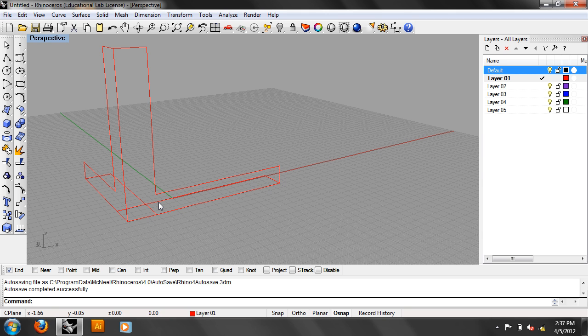If you want to try that with your drawings, what you could do is, for our house, let's say, you trace the edges of our facade, but instead of extruding it, just make it a planar surface, okay? Then you would basically trace that edge on the inside of the house, and that's a surface. And then you would surface the skin of the windows between the two, and then you'd surface the top of it. So then you have your exterior, your interior finished wall.